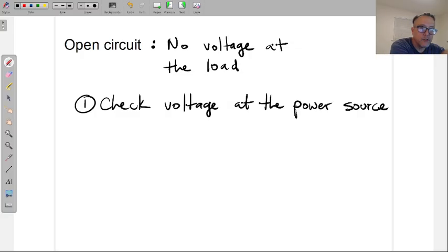I want to go and make sure that I'm starting with voltage. And then when I get to the panel, tripped breaker. Now I know how to go into my tripped breaker situation. Reset the breaker, trips fast, ground fault or short circuit, and then go through the short circuit and ground fault steps. Trips over a long period of time, well, maybe something in this outlet or circuit is overloaded, right? So we know how to approach a tripped breaker.